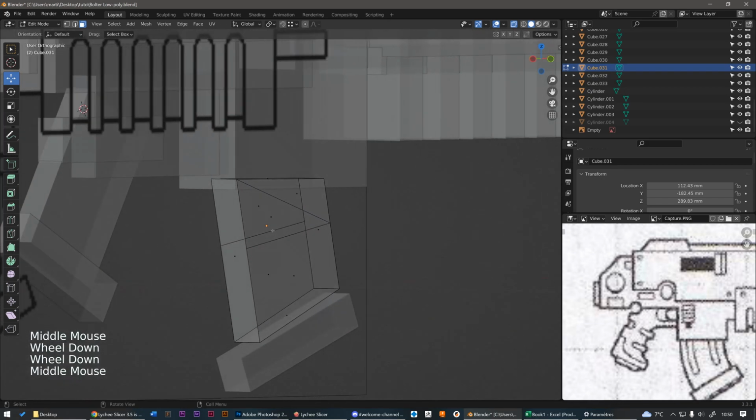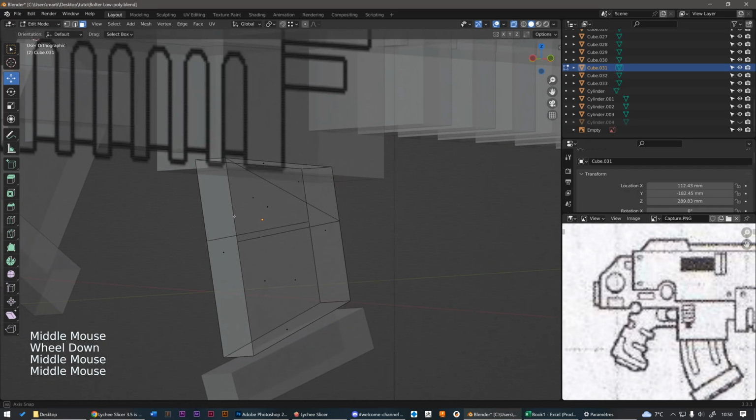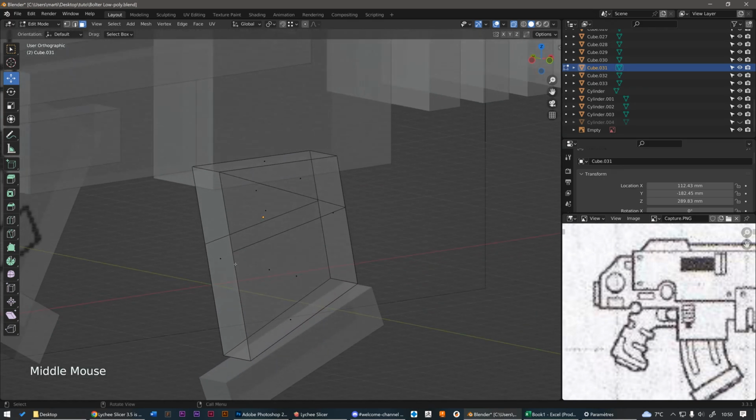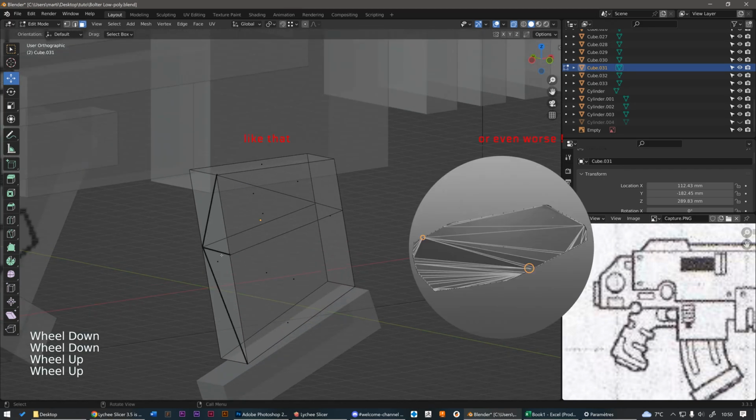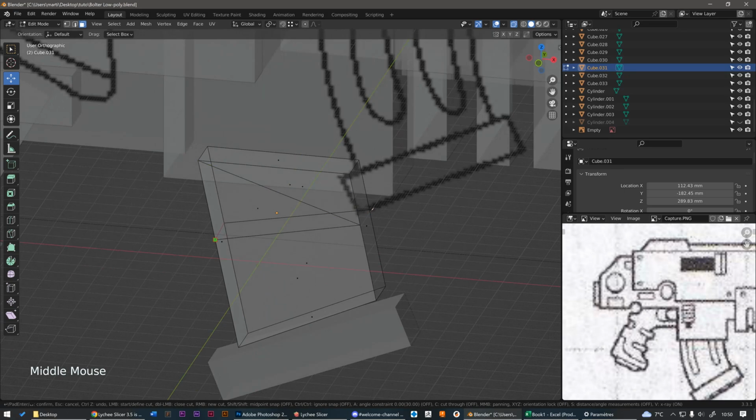And there we have a 6-vertex face, what is called an n-gon. We'll talk about n-gons later, but most of the time it's not good because with so many vertices, we have absolutely no control over how the face will then be cut into triangles. It's very, very dirty. So when we cut faces, we try to do it this way, creating what we call an edge loop.